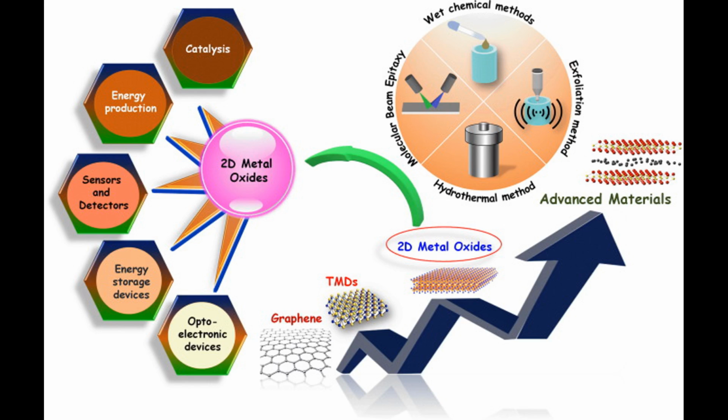On state, VGS > VTH. When the gate voltage, VGS, exceeds the threshold voltage, VTH, the NMOS transistor enters the on state. In this state, the electric field from the gate voltage creates a conductive channel in the semiconductor material between the source and drain. Electrons flow from the source to the drain through this channel, resulting in a low resistance path and allowing current to flow between the terminals.